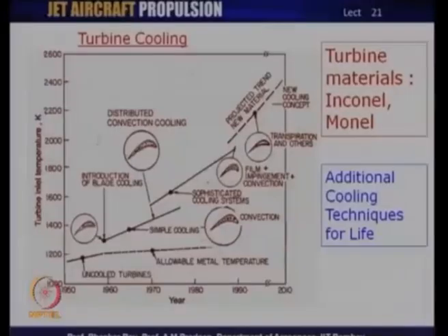Now, to render that kind of life with higher operating conditions requires very extensive cooling technology built into the typical turbine blades, and this is what this combination cooling, the film and impingement cooling, is essentially trying to achieve: that at such high temperatures the turbine blade without the cooling would have got charred in a matter of seconds.